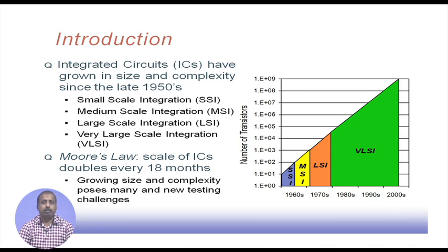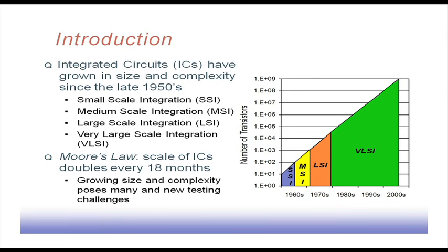Apart from the inherent challenge, that is, the number of devices or transistors per chip has gone up, the other issues include the power consumption of the chip, which has gone up because so many devices are there. So, in the testing phase also we need to address the power issue, and we need to address the temperature issue. The different portions of the chip become hot differently.